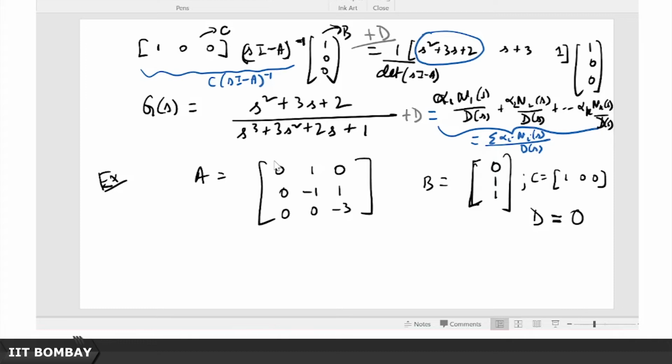So that is why we generally do not go for PID controllers in their rudimentary form, because they cannot be realized using state space realization, for the simple reason that they are not strictly proper or biproper, they are just improper. Okay, so not just PID controllers, any time someone asks you to realize an improper transfer function using state space, you shouldn't even try, you should immediately say nothing doing, can't be done, it's impossible. So that's an explanation that had been long time pending. I had promised this, so I thought I'll make good on the promise now.